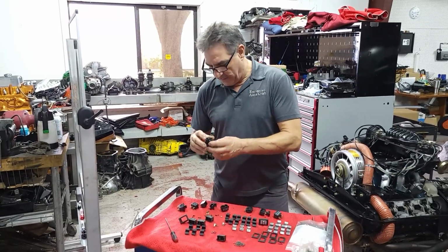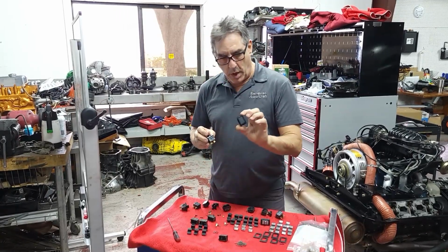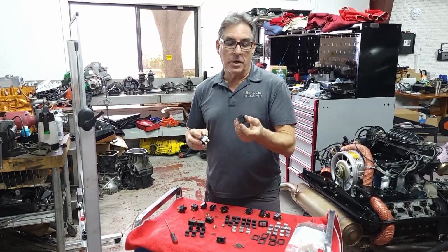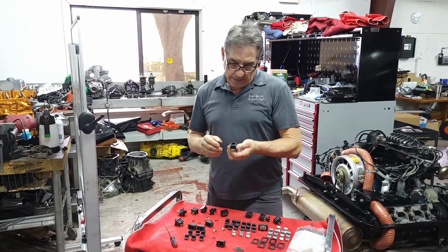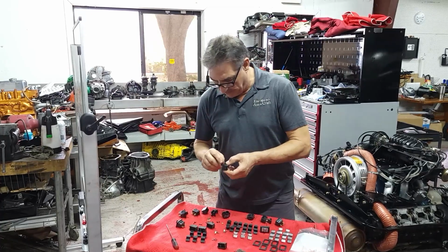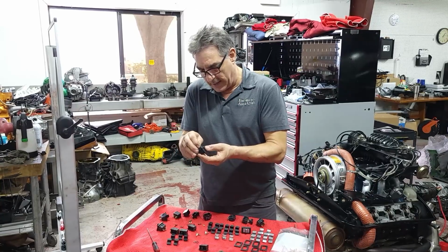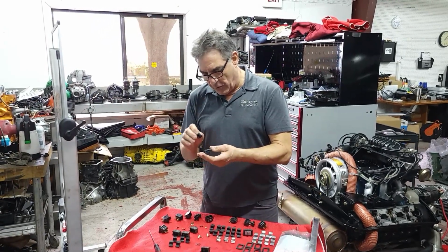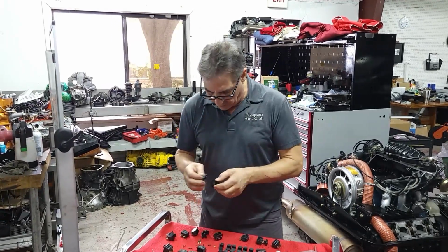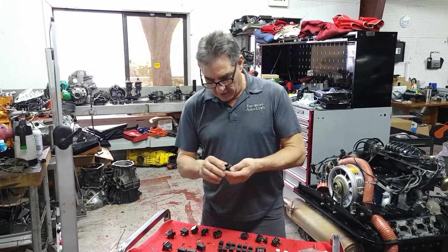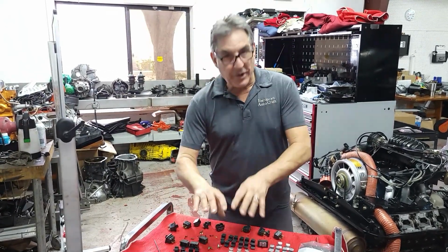So there's a number of these switches out on the market. These are the ones actually manufactured through Porsche, and this is one that's an aftermarket switch. These are kind of sloppy. They don't feel good. They last, but the same thing can happen. The little pin breaks on the toggle and causes it to go sideways. I've tried to replace the toggles in these aftermarket switches too. They don't always work out. The internals aren't the same. It's just not a real good quality replacement. So we don't need that.